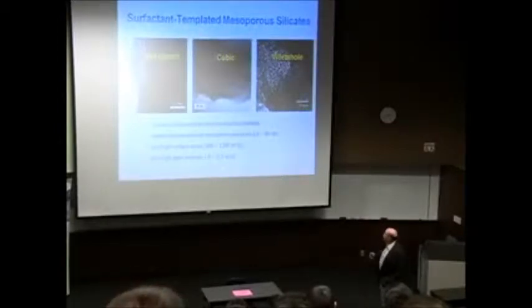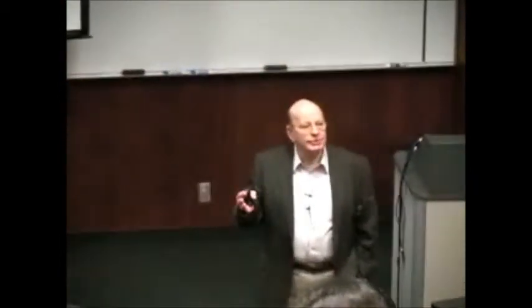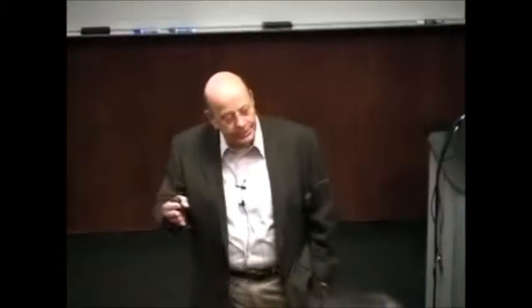When you achieve a void volume of 3.5 cc's per gram with a silica, you're talking about 80% or more of the silica being empty space. And that's remarkable, to have a solid where you have that much accessible volume in which to do chemistry.